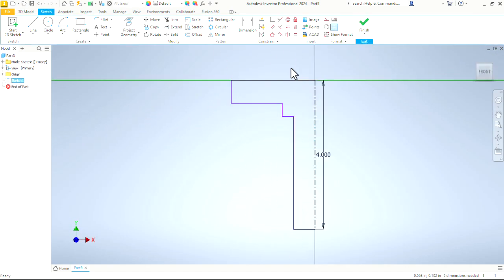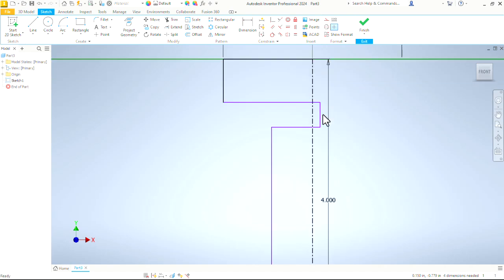So what that means is that this distance from center line to the edge is just the radius of our part. But once I have it defined as a center line, look what happens. It creates a dimension that is a diameter that goes all the way across to an imaginary line out the other side. I want to give that a diameter of 2.5 inches. Notice how sometimes things adjust, may not go exactly where we want them after we apply a dimension.